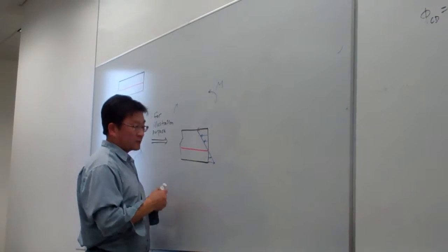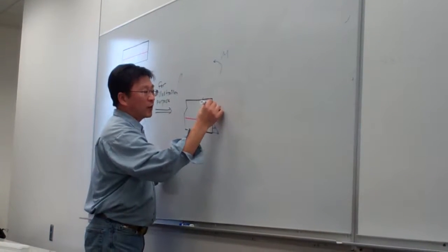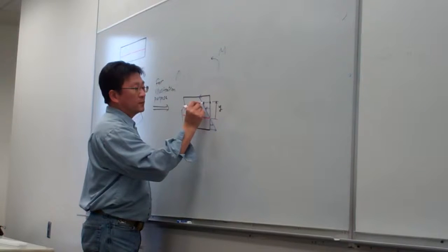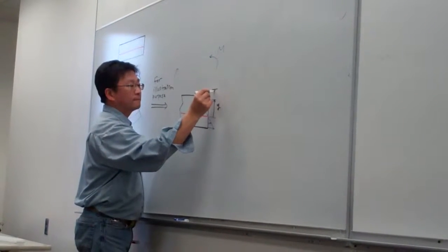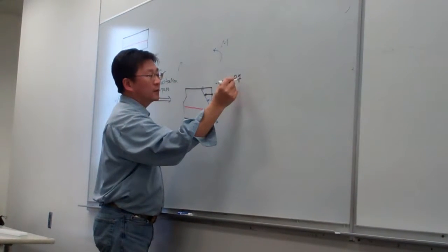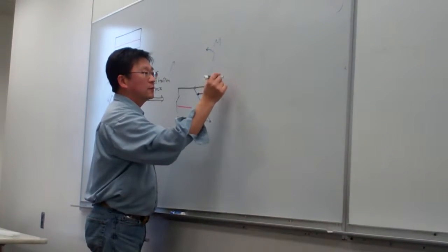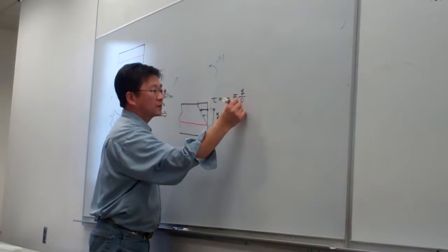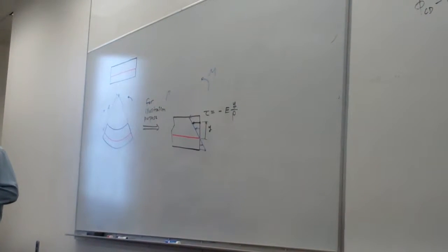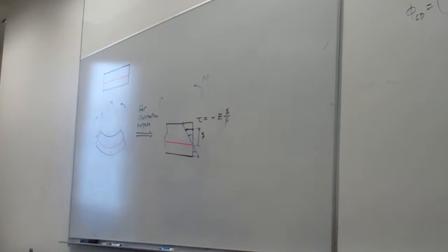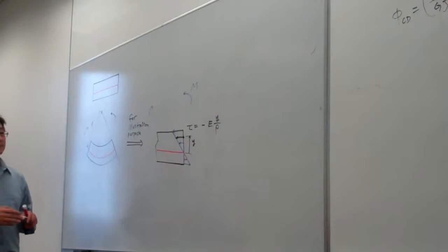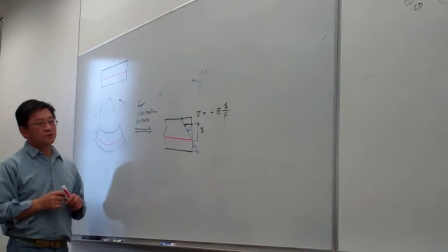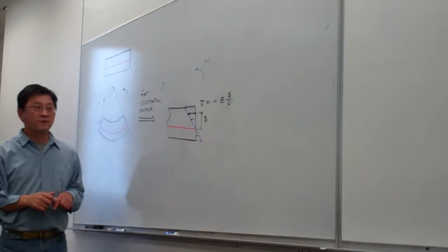And for example, if we're interested in this point, we give a location, y. And at this site, the stress equals sigma equals minus E y over rho. Like this, right? Is that the one I left from last time? Can you double check that one? You said sigma, not tau. Oh yes, sigma. So this is what we have done from Friday last week.